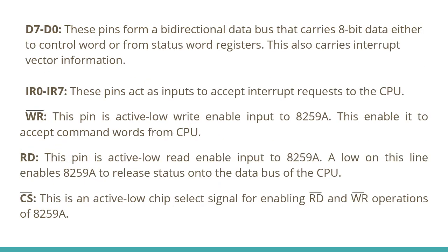The D7 to D0 pins. These pins form a bidirectional data bus. These pins carry 8-bit data either to the control word or from the status word registers. This also carries interrupt vector information.